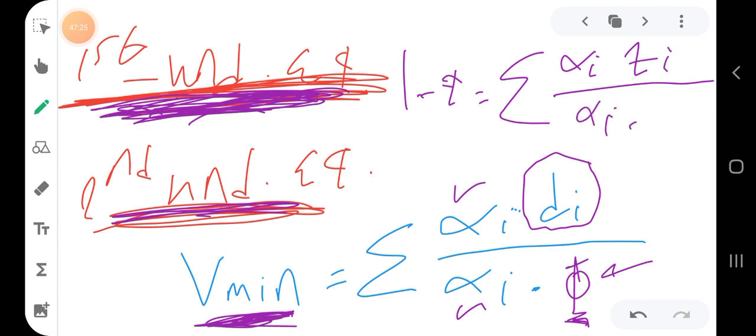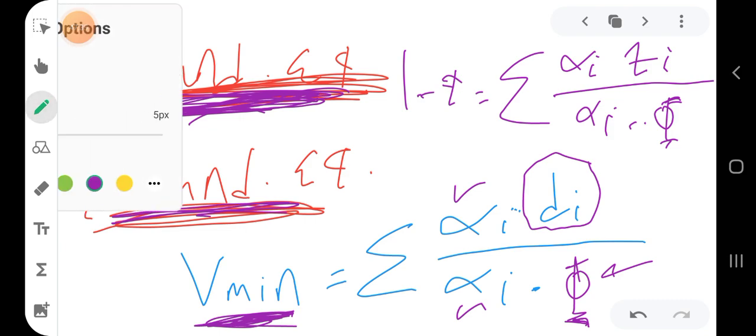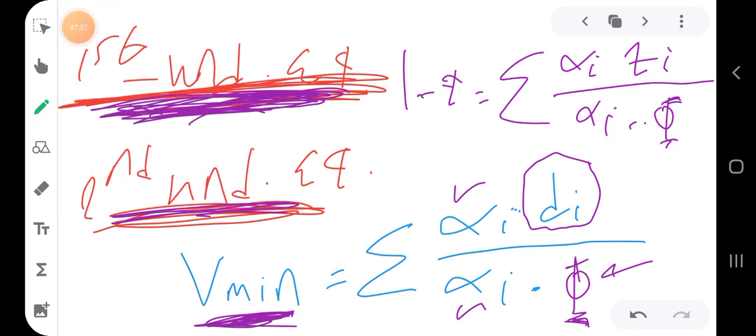Okay, so as you know, this value of Q is known from the state of the feed, whether it's saturated liquid, saturated vapor, etc. So you know this, and this alpha you can know, it is a property, and usually the composition in the feed for all components is given, so you can solve this equation to get a value of phi using a solver.